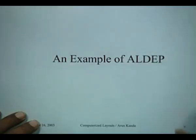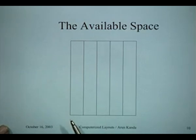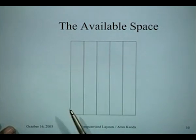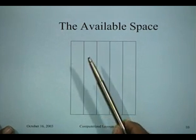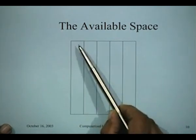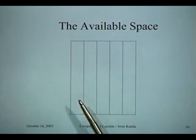Now let's try to get an idea of what the whole thing will look like if you follow this procedure of LDEP. We start with the available space. Let us say there are 4 departments, let's call them A, B, C and D, and we want to locate them in this particular space. We are constrained by this width. We imagine that each department is cut out on a strip of constant width, and we cut out the length depending upon the area of the department, which we know, and we allocate that in this space.